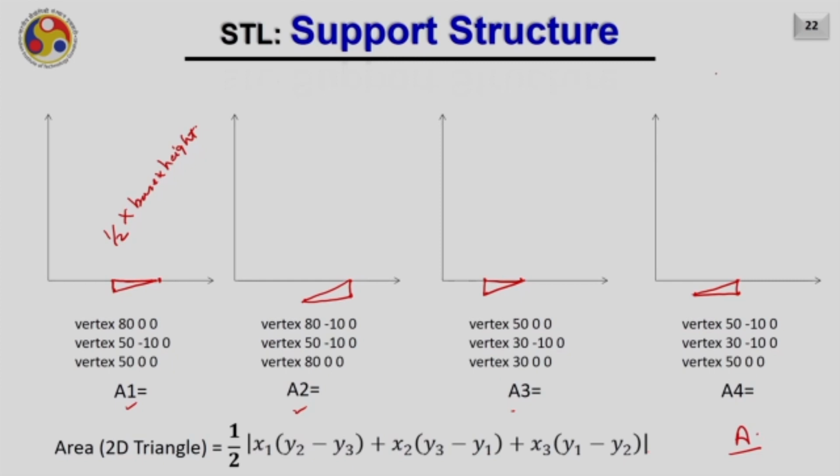If it is required to find the volume, then you can multiply the summation of all the projected areas, in this case we have 4 triangles, into the average height. This projected height can be calculated by taking the z components of the 3 vertices and averaging them.